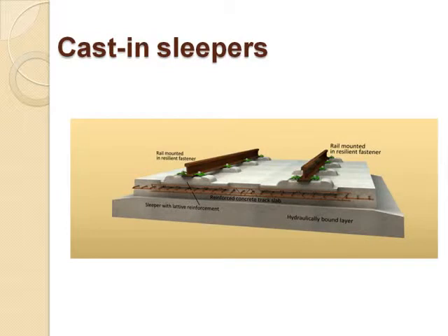Casing sleepers is that the rail is mounted on a sleeper by means of a resilient base plate. The sleeper is cased into a concrete track slab. The base slab or trough section is slip-formed. Track panels with the rail mounted on the sleepers are then set up, while